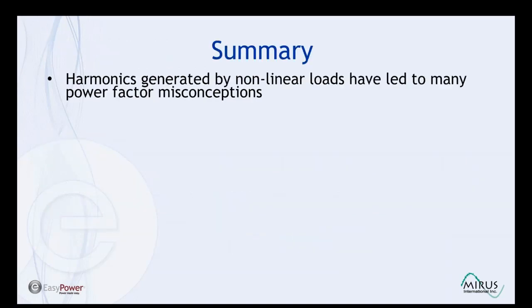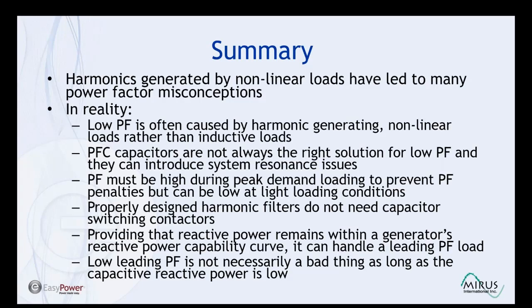So in summary then, we know that harmonics generated by nonlinear loads have led to many power factor misconceptions. But in reality, low power factor is often caused by harmonic generating nonlinear loads rather than inductive loads. Power factor correction capacitors are not always the right solution for low power factor, and they can introduce system resonance issues. Power factor must be high during peak demand loading to prevent power factor penalties, but can be low at lighter loading conditions.